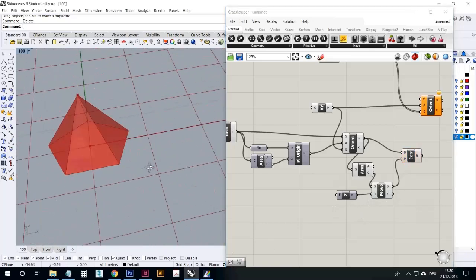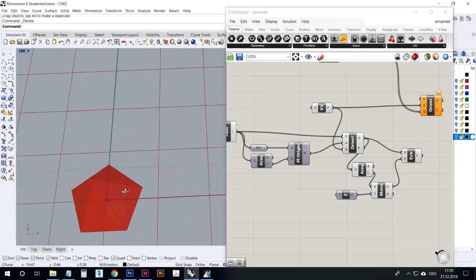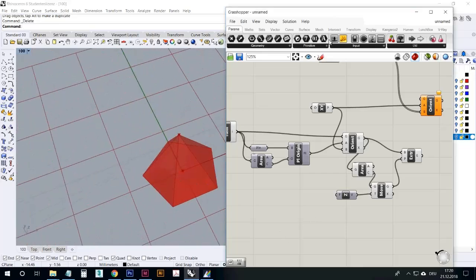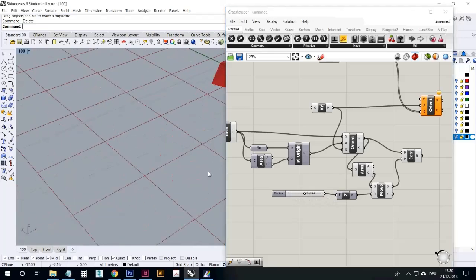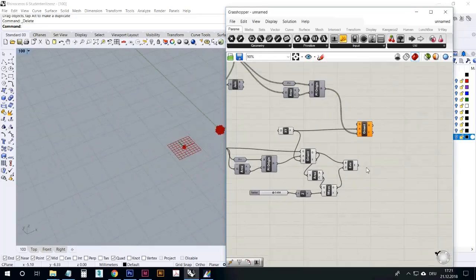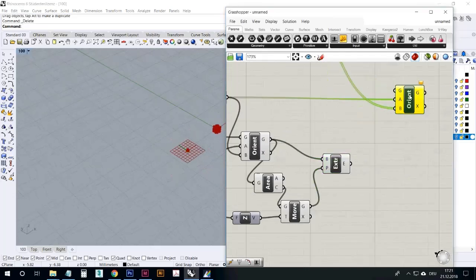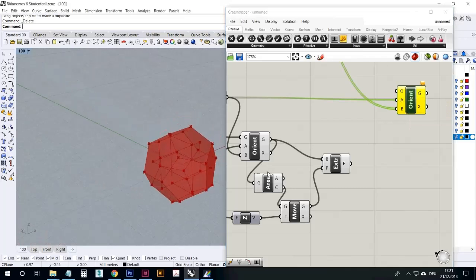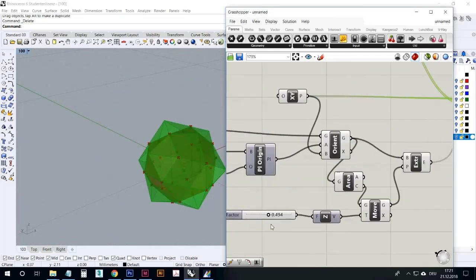So now you have a sort of five-sided pyramid here, and we need to have also a slider, of course, to affect the height. And it goes in there, and you can pull up and down like that. And then, oops, sorry, this extrusion is simply to be put into the G here, and then it lands all over the place on the icosahedron, on the dodecahedron, like that. And then if we pull back and forth, we see that it gets stellated.